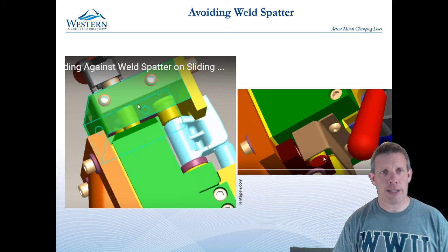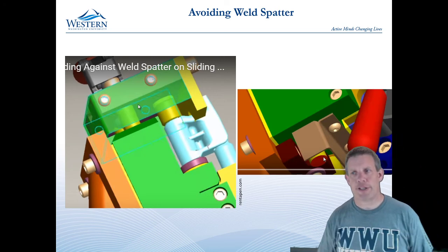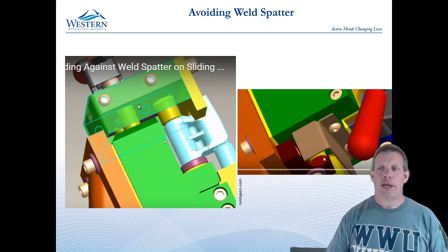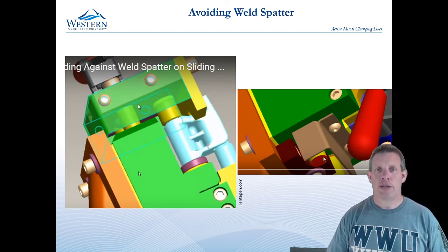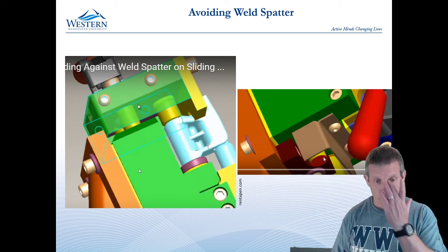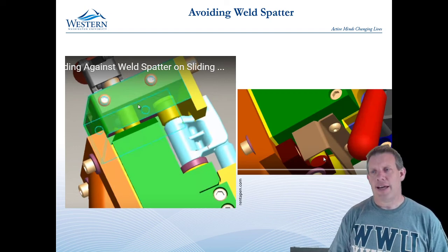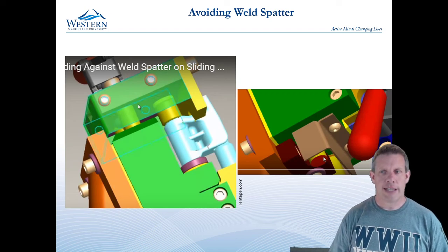All right, and then one last thought for welding fixtures especially is that you will often have to put in weld spatter deflectors. And so spatter comes out, if you remember from 231 when you were welding, there was stuff flying all over the place, and that will stick to metal and is hard work to get it off.